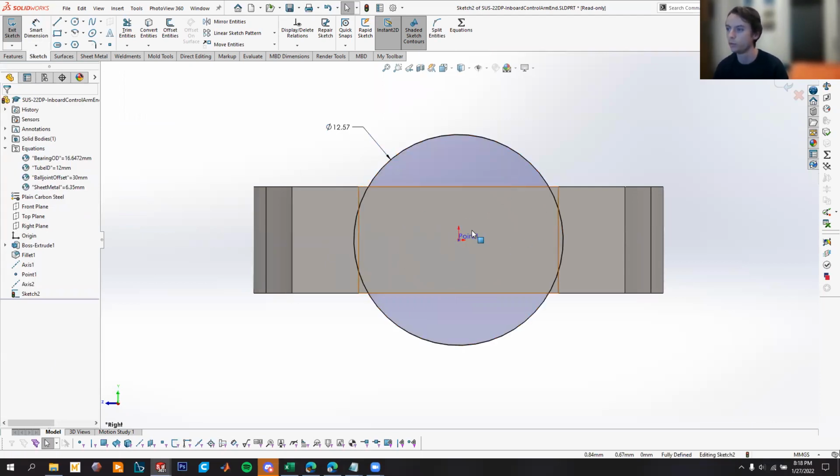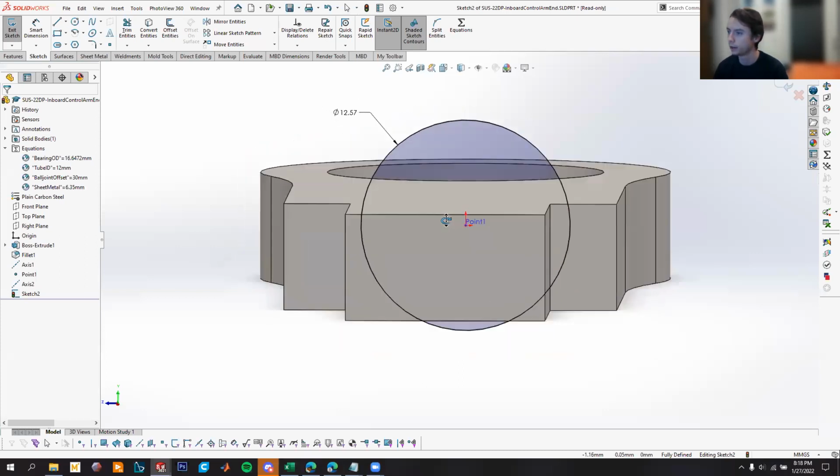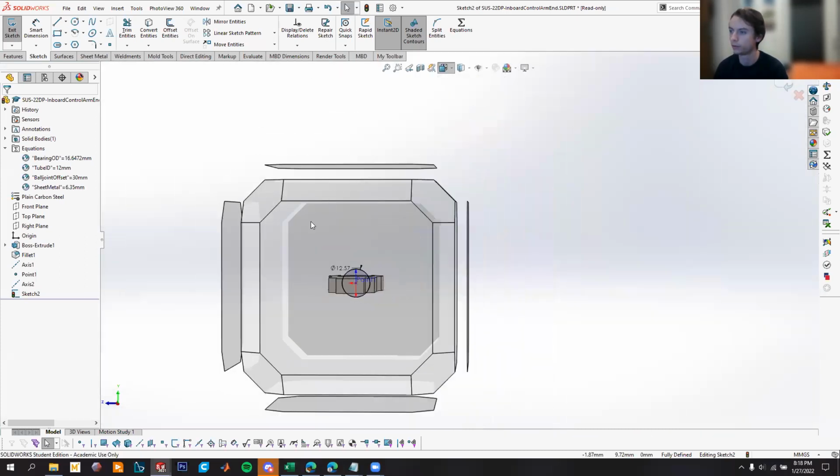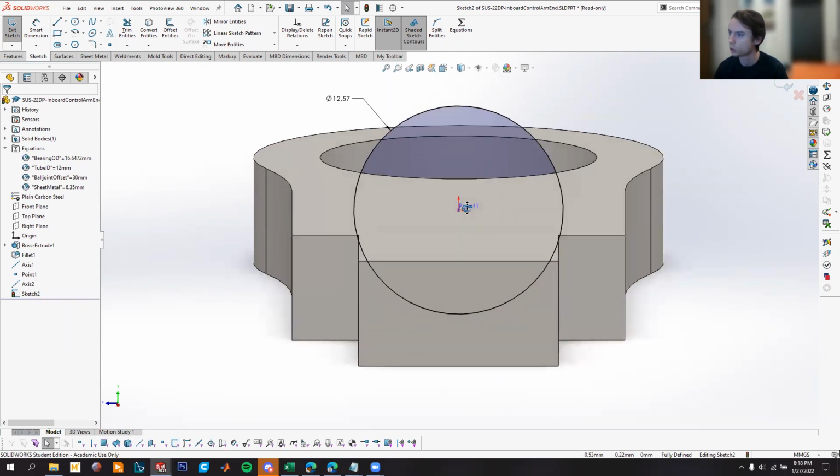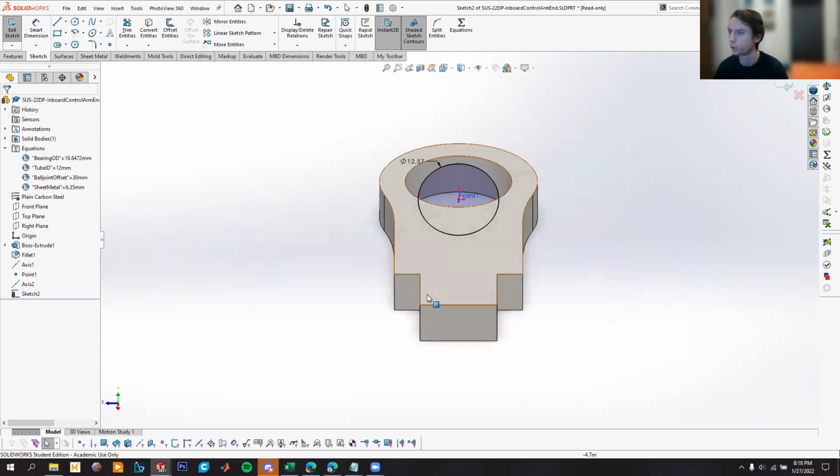Okay, so with the 12 millimeter inner, we would be shaving off just these four corners on a bench grinder. That's real easy. And we still have sufficient contact area inside to weld. So if you made those in millimeters, 12 millimeters is a good size for